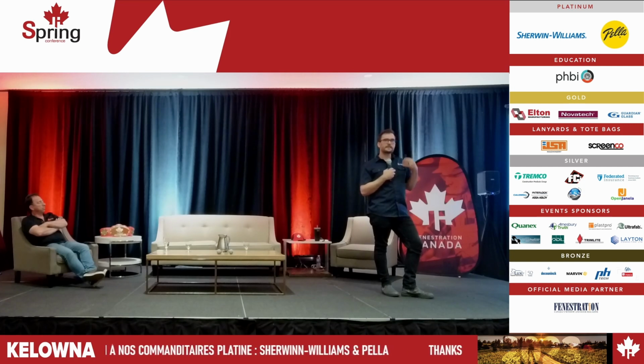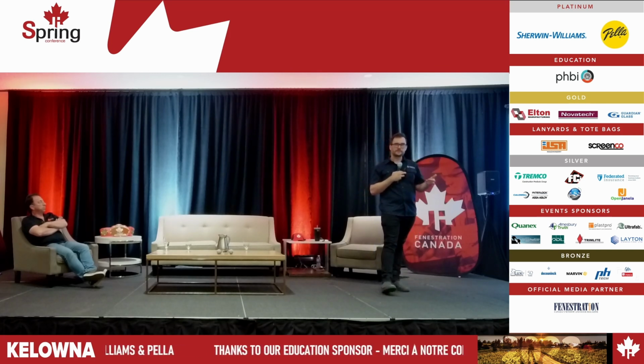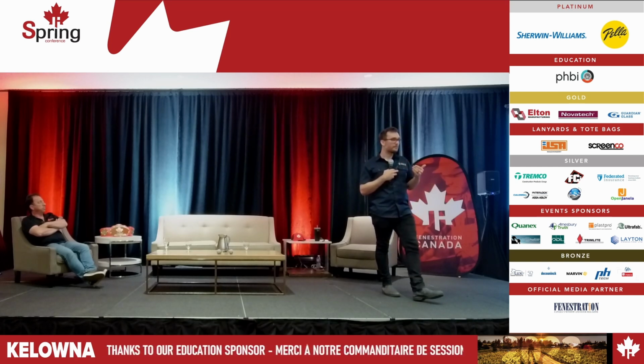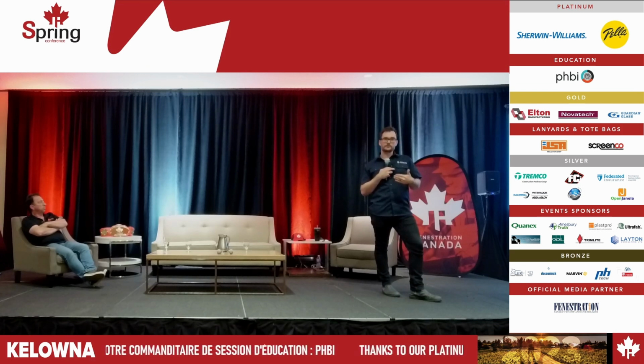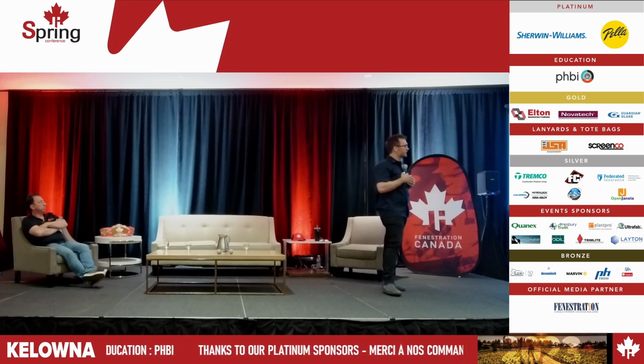So that's the thing that we have to be looking at and educating our clients on too. Building orientation is very key, because if you have a project that has a lot of windows facing north, you want to be educating your clients and builders, saying, hey, you're not benefiting from a lot of passive solar gains in this case. We might want to look at a higher performing U value for performance. Or there's going to be something your energy advisor is going to be speccing, in the way of under slab insulation or better quality air tightness or something to make up for it. So orientation is very key.